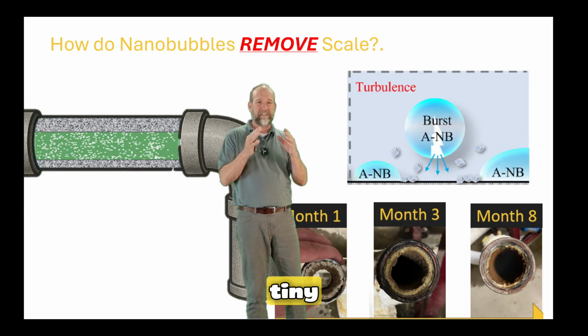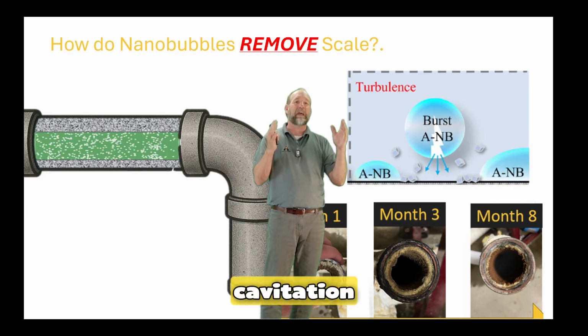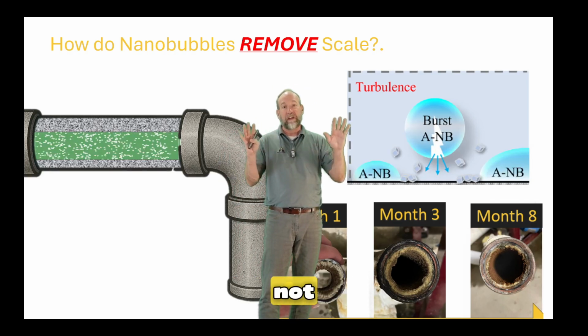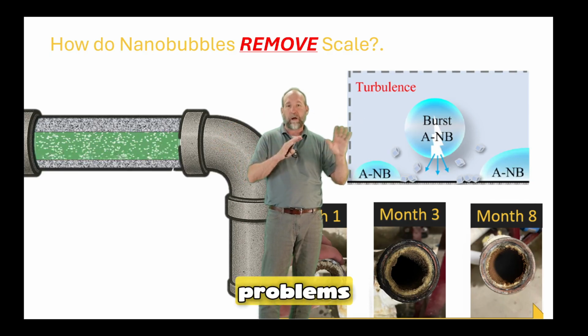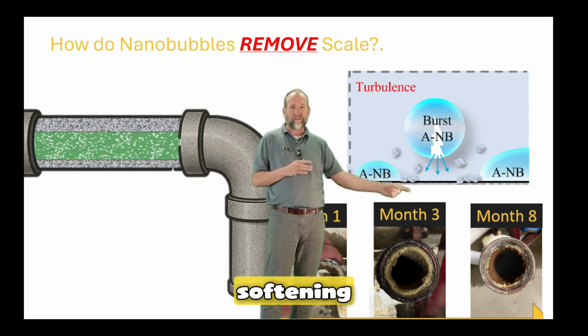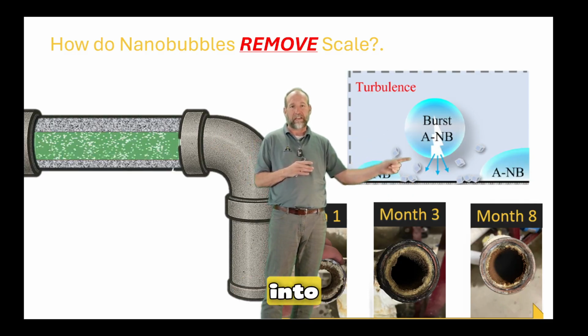Very, very tiny. When I say a little microcavitation, don't freak out. That's not some sort of a cavitation that's going to cause pitting or impeller problems or things like that. It's basically just softening up the scale and bringing it back into solution.